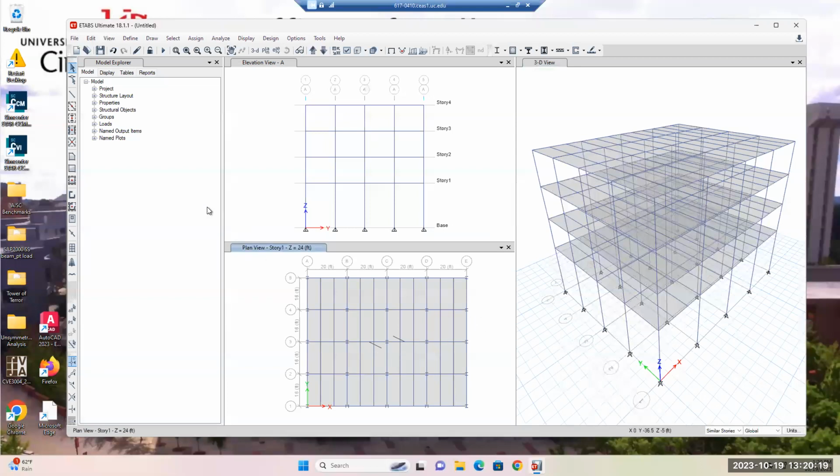beams. And so the reason why I applied a diaphragm to my decking, now that I have everything set up, I have my structure set up the way I want. If I wanted to do a different slab on the top roof, I can come over here and say, just this one story is what I want to change. If I had chosen all stories and selected this, then it chooses all stories. You can see this dashed line over here. But I want them all the same.